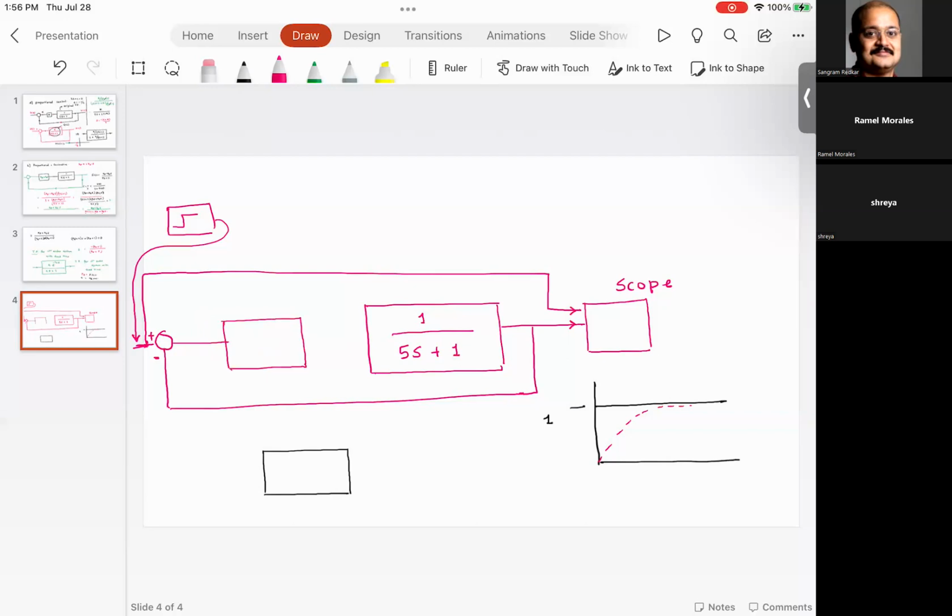I have a quick question. Yeah. Just wanted to clarify, so gain block, what is it exactly? The gain block is KP, the proportional control. Okay, it's the K value that adjusts it. Yes. So we could increase the number, like to 50, and see the graph. Yeah, if I try 50, it will reach the line, but there will be some steady state error.